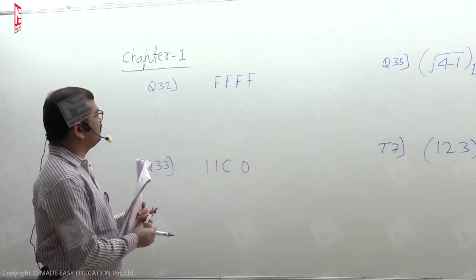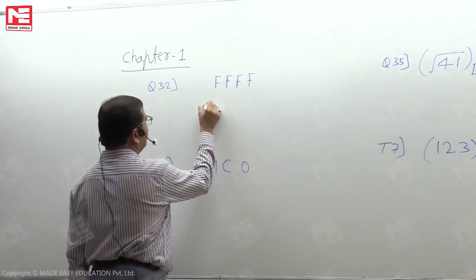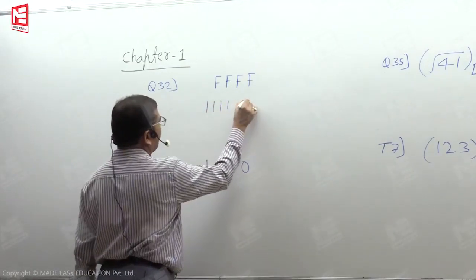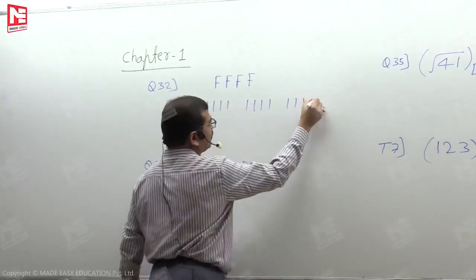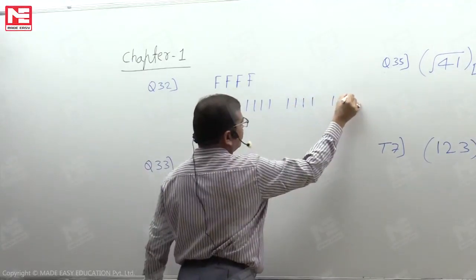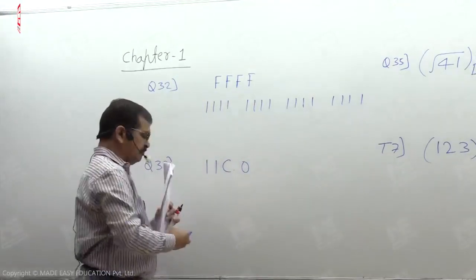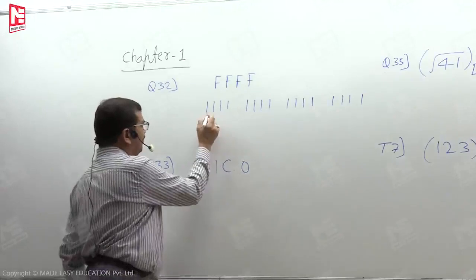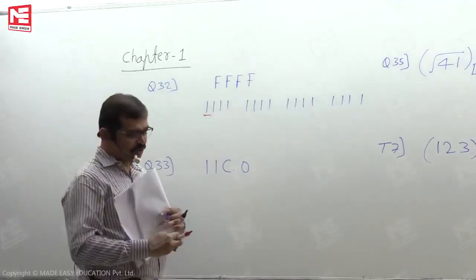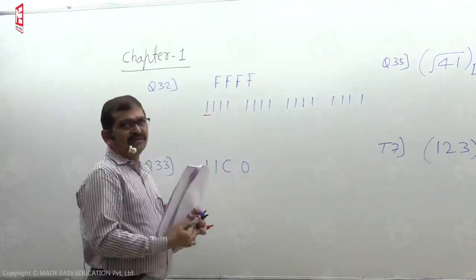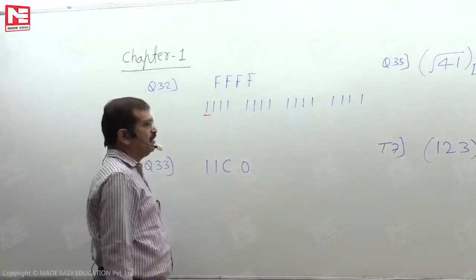So if you look here, its magnitude is asked in decimal form. F will be all 4 bits 1. The number is in the 2's complement form. Once the MSB bit is 1, number is negative. So the magnitude is not the true magnitude. The magnitude is in 2's complement form. To read the decimal equivalent value for the magnitude, we need to perform the 2's complement operation on this.